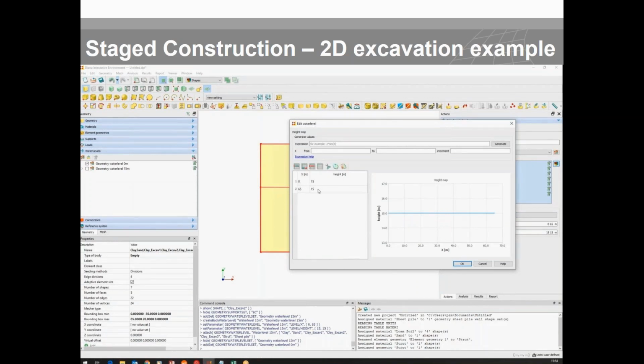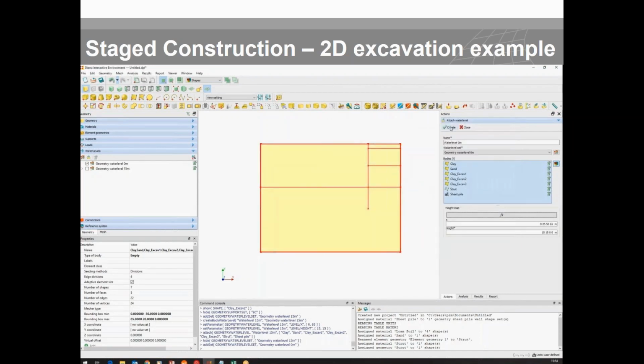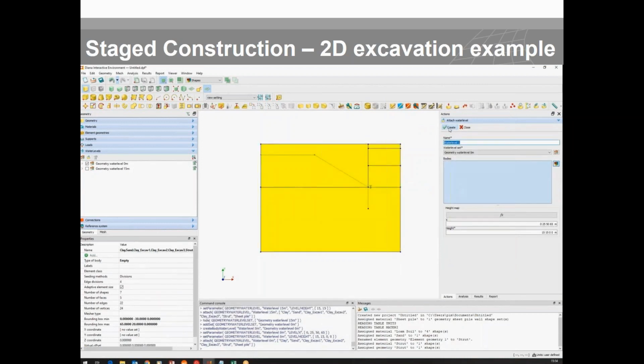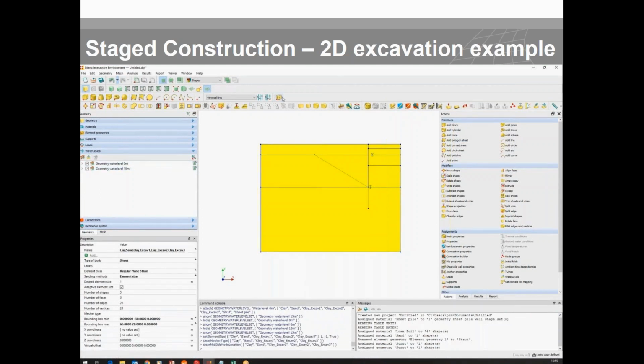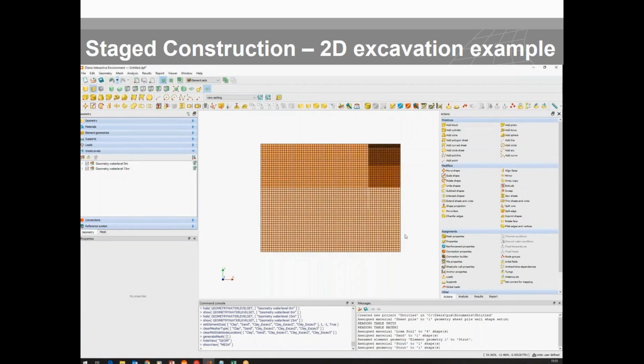In terms of the profile now, at 0 is 15, then this is the start of the deviation and the dewatering profile at 25 meter, 50 and 65. If I click create, this is how the profile of the dewatering is going to take form in the model. So we have two water levels. One is 15 and another one is when the dewatering level goes to 0.